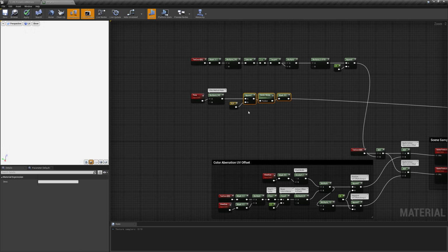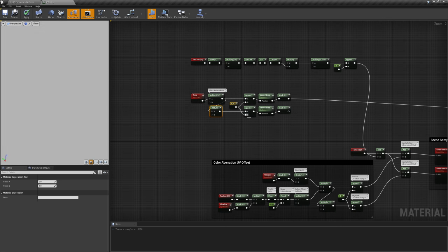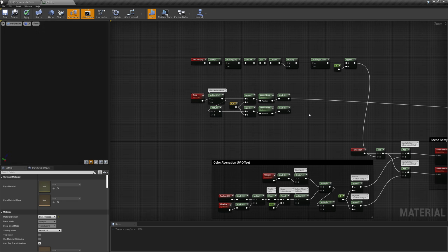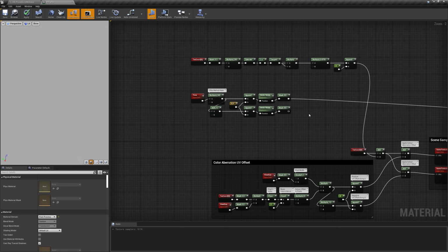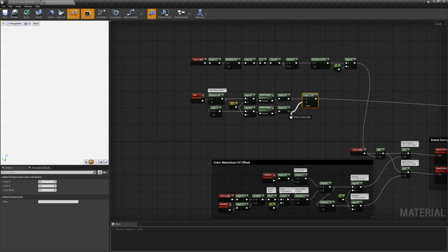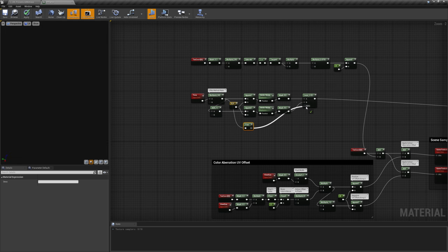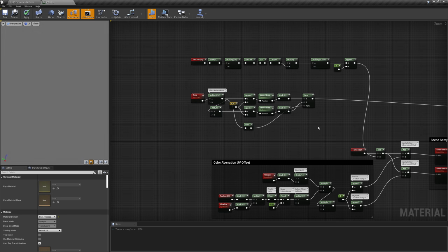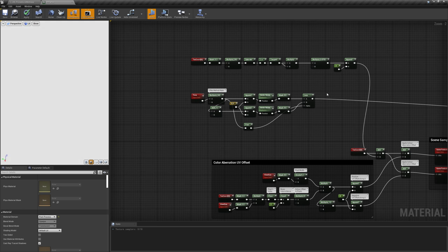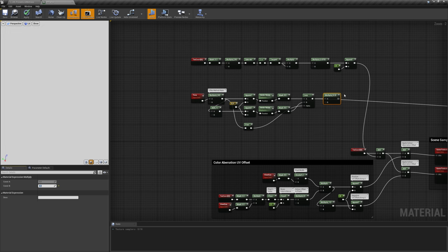Now, let's do the same again, but let's grab the noise value that corresponds to the next frame. Now, I have one vector noise outputting the current frame random intensity, and the other one outputting the next frame one. I can interpolate the two by using the fractional part of the frame time. Notice how now the random value is not jumping from one value to another, but is smoothly transitioning. Now we can remap the range of this noise and connect everything to what we did before.